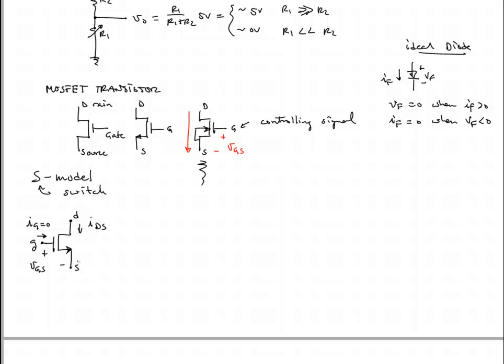If you have a current source whose current is dependent on some voltage, you really have a 3 or maybe even 4-terminal device. We just wouldn't usually draw terminals for the controlling signal, and that's what this transistor is kind of like. We'll eventually see that one of the ways the transistor behaves is as a current source, but that's down the way. Right now we're going to look at it just as operating as a switch.